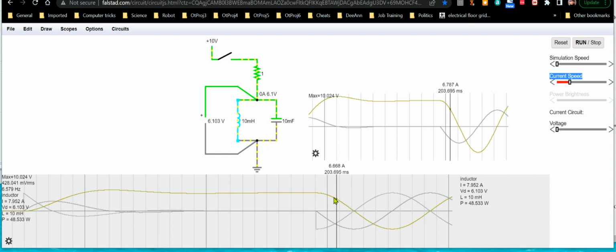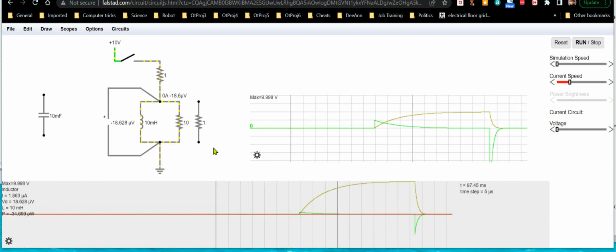But when an inductor is discharging, like I was talking about a few minutes ago with the 10 ohm versus 1 ohm resistor, that inductor will generate whatever voltage it has to in order to maintain that current. It started out at 10 amps and is trying to maintain that 10 amps. The moment I disconnected that source, it wants to keep that flowing, and whether I put a 1 ohm, 10 ohm or 100 ohm resistor in there, it'll generate whatever voltage it needs to try to maintain that current level.